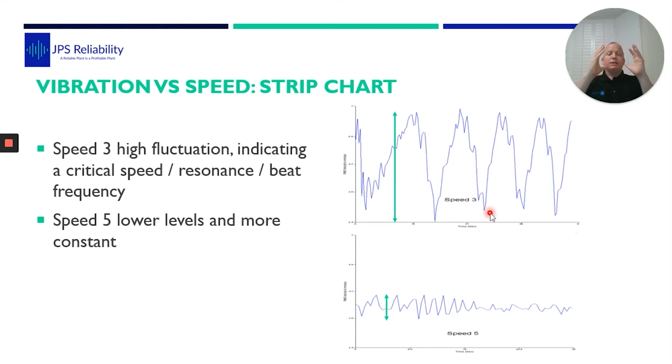So that motor there, when it's running at set point 3, highly directional, is juddering, with a motion coming around. You put it up to set point 5 and it's a lot smoother. So down here, you can see it's a much smoother motion. So we're getting this data up to try and show, to explain to the asset owner that the problem is resonance.